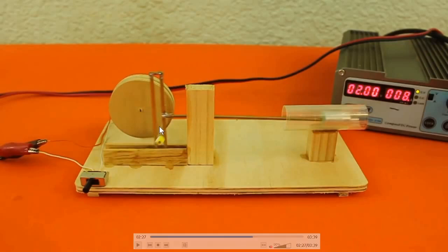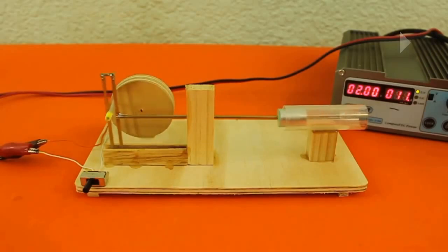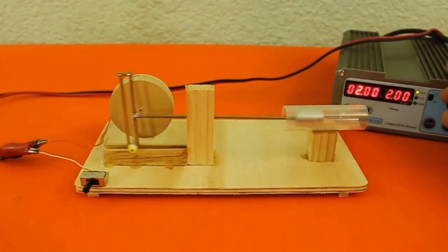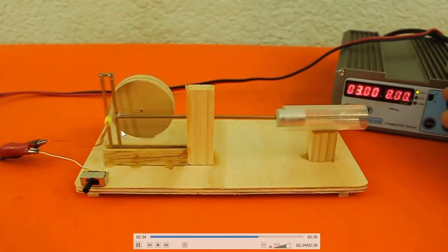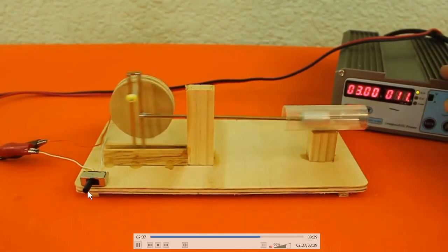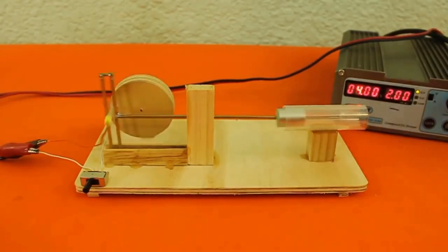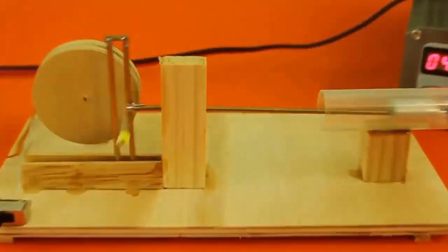So this is now a sliding pair. As the crank moves, this will slide on this connecting rod end, and the connecting rod's other part will move with the piston, which is constrained in this cylinder. Okay, this is Scotch yoke mechanism. This is also an interesting mechanism. And here he used a motor connected to the crank, to rotate the crank. You can see the switch. So this is rotating with the electric motor.